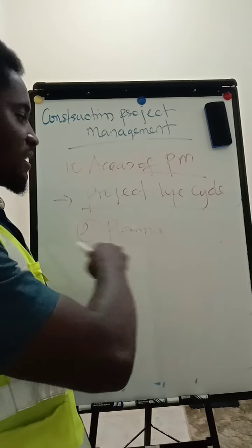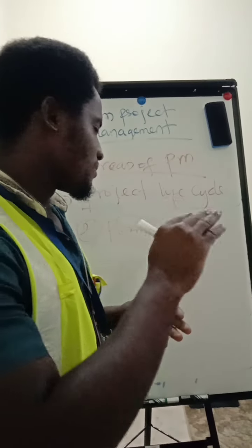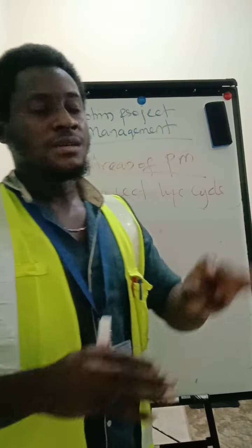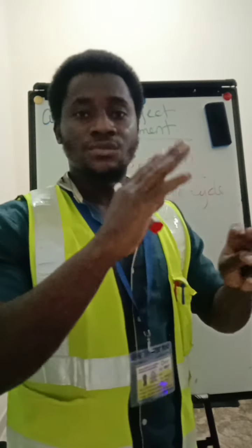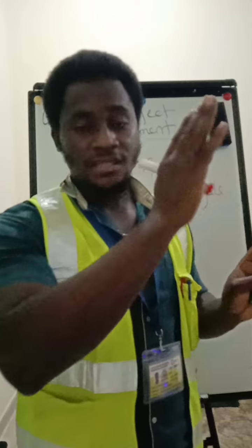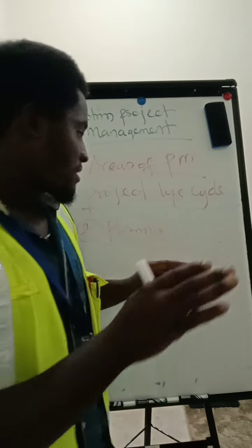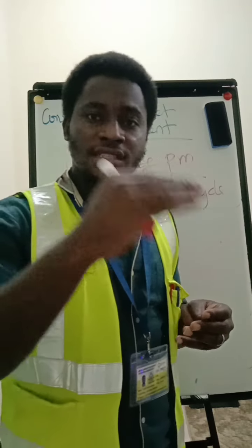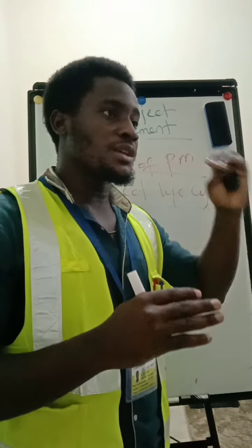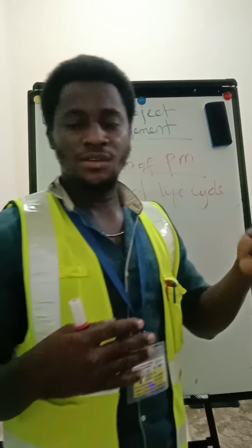So in the work breakdown structure, we have the design, and then move from the design to the execution of the work. We start carrying out execution. We define the construction activity into three different parts, maybe the first phase, the second phase, and the third phase. We'll break them down very well, which is the work breakdown structure we are discussing, and then move to the testing and commissioning activity, breaking them down from pre-commissioning to commissioning, or testing and commissioning, inspections and all that.